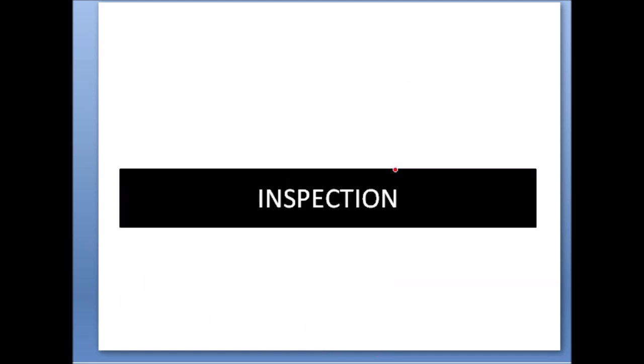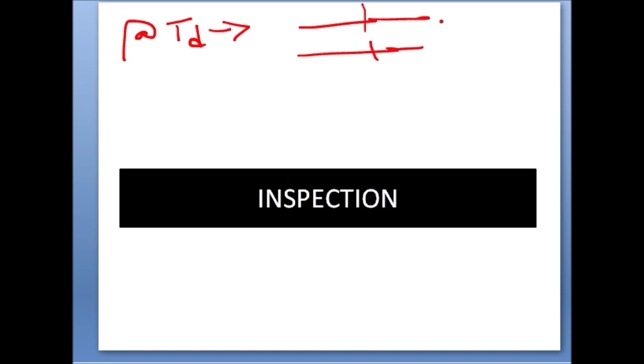Okay, so if at TD you are doing welding and bringing continuity in the track, because you have joints here, you want to remove this. Okay, so when you are doing welding, temperature was TD and position of the tongue rail was same as per standard, then you directly do welding. When it was different, based on temperature, then you have to adjust it. How we have to adjust? Just now I have told.